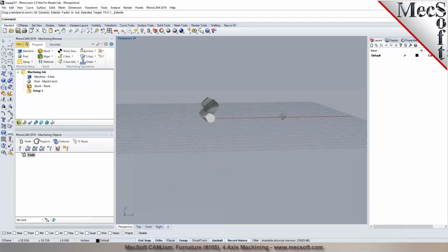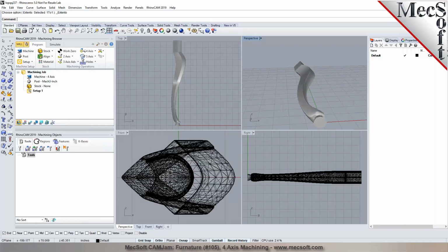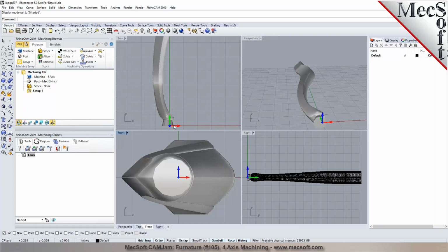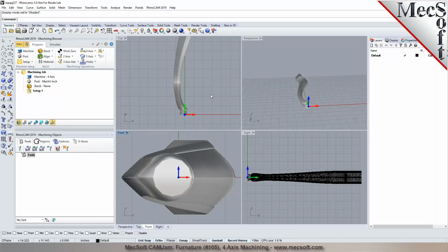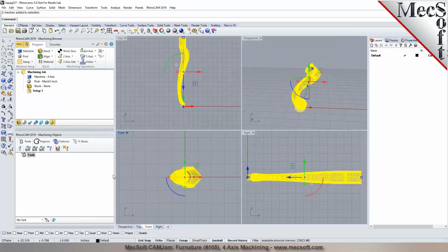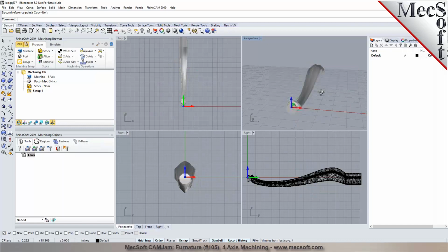So we have the part defined as you see it, and if you look at it from the front view, the 000 is over at this lower left corner. If you want to flip the part over the other way around, we can do it in Rhino. It's just a simple rotation command to flip it over. Now I can see that there are features on this part that are dipping below the center of rotation. So let's go ahead and rotate this part over by 90 degrees so we can clearly identify the areas where we can see the undercut, right?